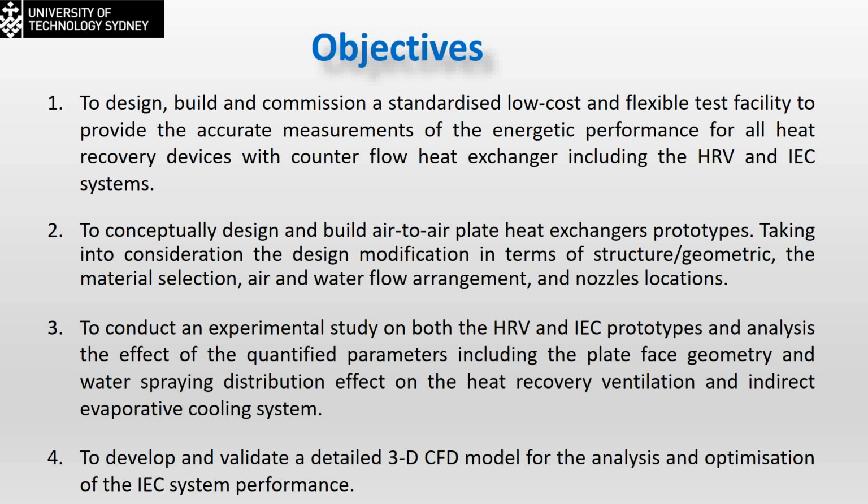Then do experimental tests for testing both systems, changing the input parameters, which can be shown in the next step, and develop a 3-dimensional CFD model. And this is actually, beside the water spraying system novelty, very novel because this is the first model which is in 3-dimension with realistic sprayers within. Usually they just consider that the water is covering the whole plate and do the simulation for that. In my case, I simulated the nozzles realistically within the heat exchanger channel.